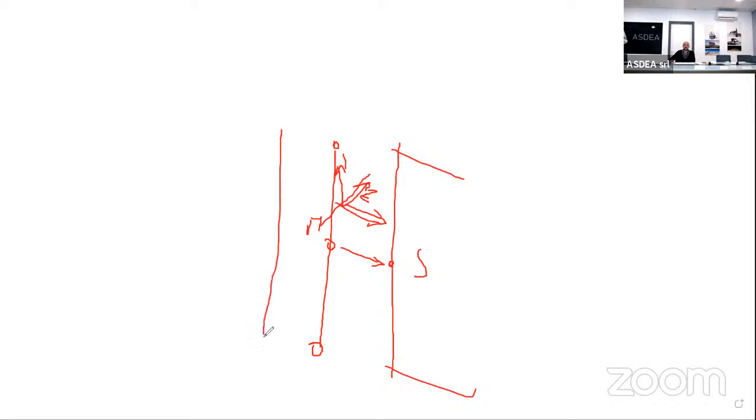And since you have a two-sided contact, so the shell is on both directions, here you need to create another interaction that goes from the master to the slave with another local axis, which is this one. Now, this is very difficult. That's why we implemented a tool, which is this one. But now probably it's difficult for you. Yes, it takes a lot of time because you have to create a lot of interactions.